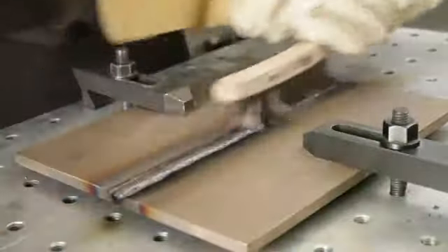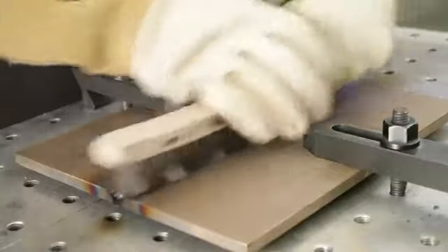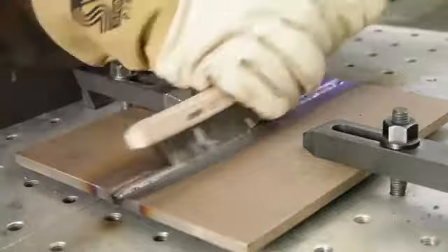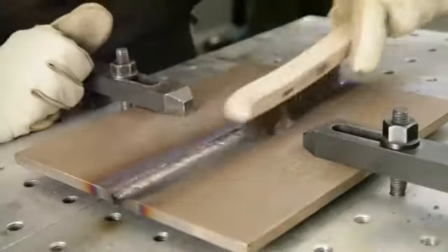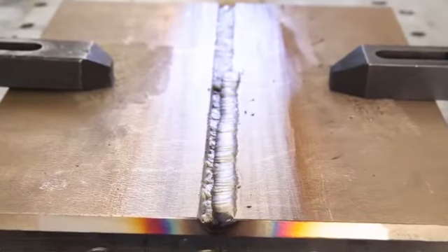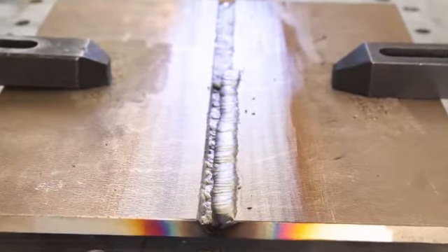After the weld is made, post-weld clean to a bright finish and visually inspect the weld to assure that it meets desired quality, the proper weld contour, and is free of defects such as cracks, undercut, and lack of fusion and penetration.